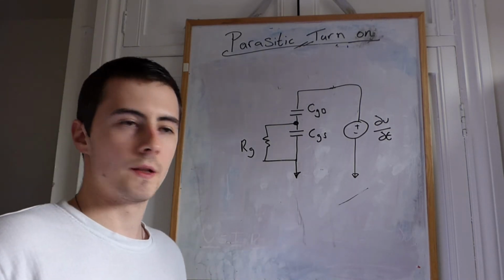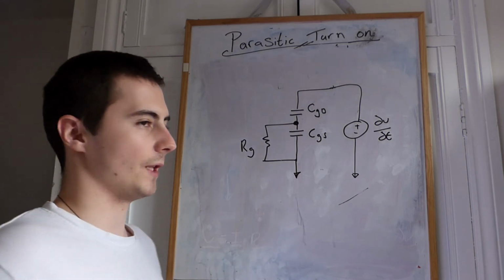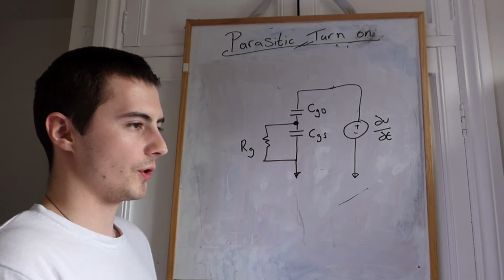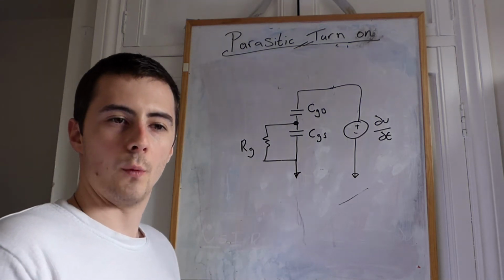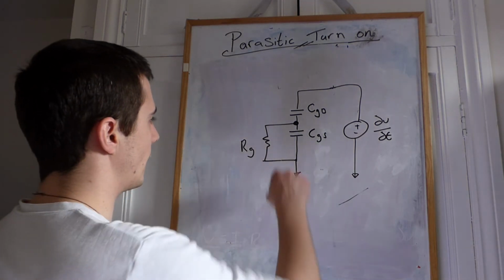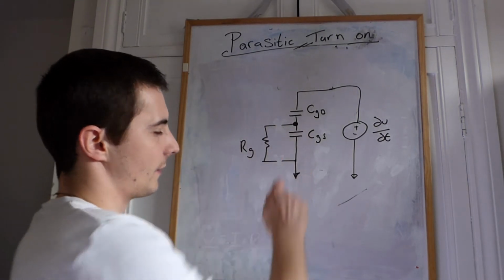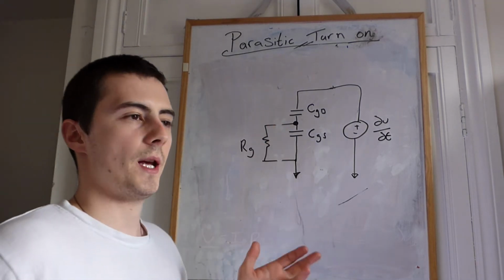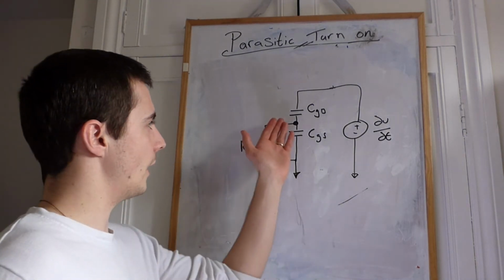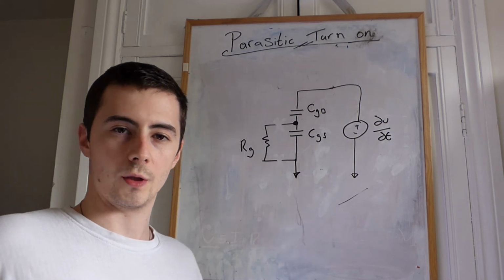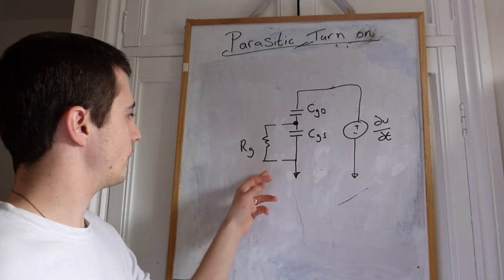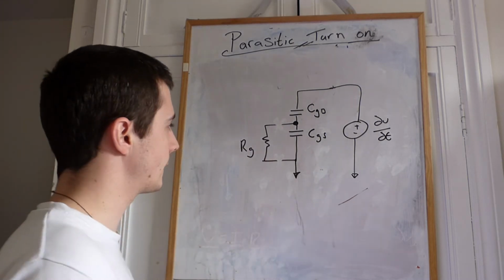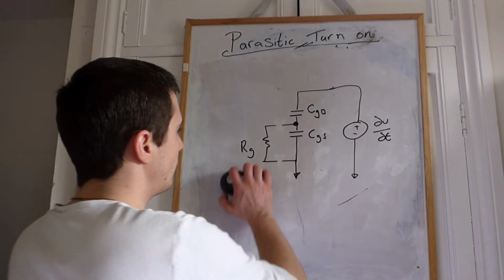Now what we're going to do is, first of all, an AC Thevenin equivalent of this circuit. We're going to figure out what the voltage source equivalent would be and what the load would be for this circuit. It's similar to DC Thevenin equivalent analysis. With DC analysis, any capacitors would be open circuits, and you would ignore them. Conversely, here we remove the resistance, similar to what you would do with the capacitances. So this resistor is now gone.